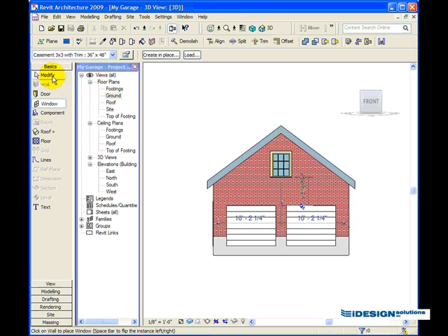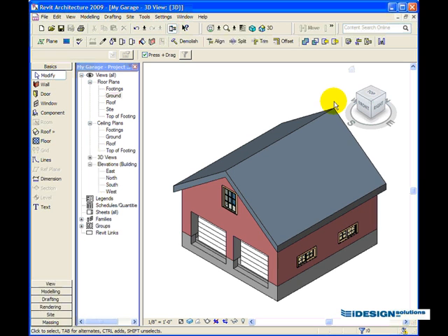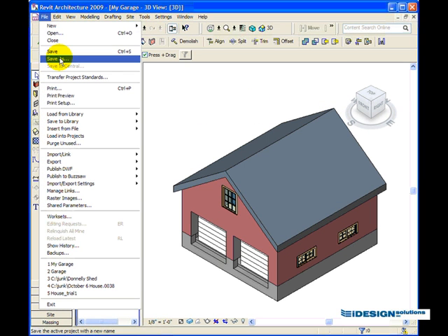We will get out of the window command by making our way to the basic panel in the design panel. Click modify, and we'll hover over the view cube so that the little house icon is displayed, and we click on the house icon to get us a 3D isometric view of the house. We have now completed the Windows insertion portion. Remember to save. File, save.